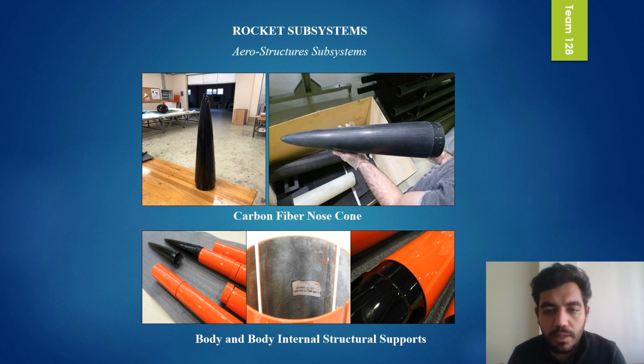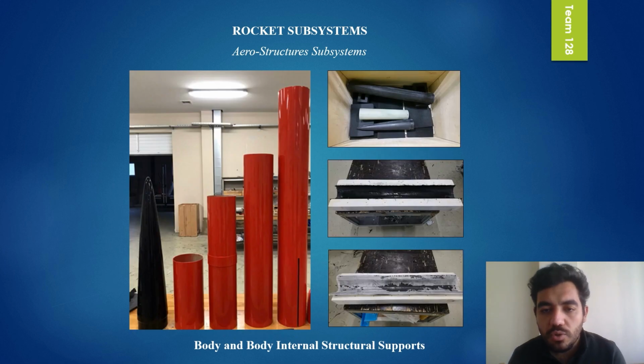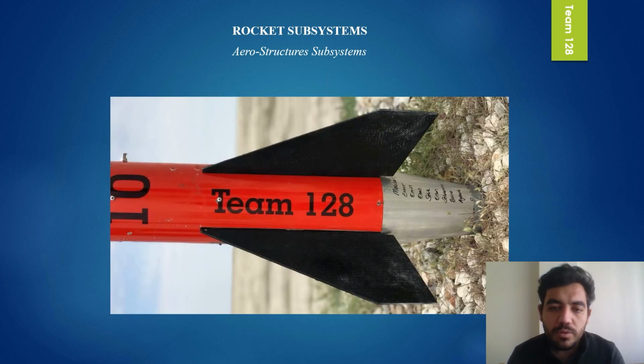The nose cone, rocket body, and fins are manufactured by the composite production method. The first body tube, the avionics section, and motor section 1 are made of glass fiber that can transmit signals. Motor section 2 is made of carbon fiber to withstand the thrust generated by the motor and the forces on the fins. For the production of fins, hand layup and vacuum infusion were applied. The fins coming out of the vacuum are fitted in the slots on the 3 centering rings and fixed with screws. The fin system is driven into the body through the slits opened on motor section 2, and the system is fixed with screws through the body to the centering rings.